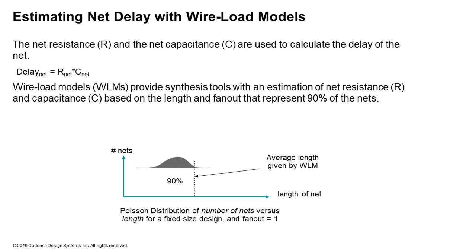So obviously these are statistically weighted, and you have these wire loads that are sort of pessimistic because of that inherent statistical behavior, and they might be unreliable for some designs. But because they provide a good estimate, you still could use them for critical path analysis, and people have been using them, especially right after synthesis stage and so on and so forth, and also as a good starting point for synthesis.